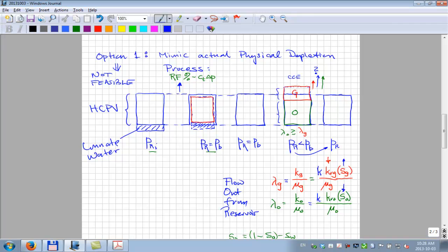And there are, in fact, some reservoirs that behave like that, because the permeability is so high that when the gas comes out of solution, pops up to the top, like something that happens in the bathtub. Okay? Because it has a high permeability, the gas comes out of solution, pops straight to the top. So if you produce at the bottom of the reservoir, all you produce is oil. Gas comes out, pushes the oil down. It's one of the highest recovery efficiencies you can get.